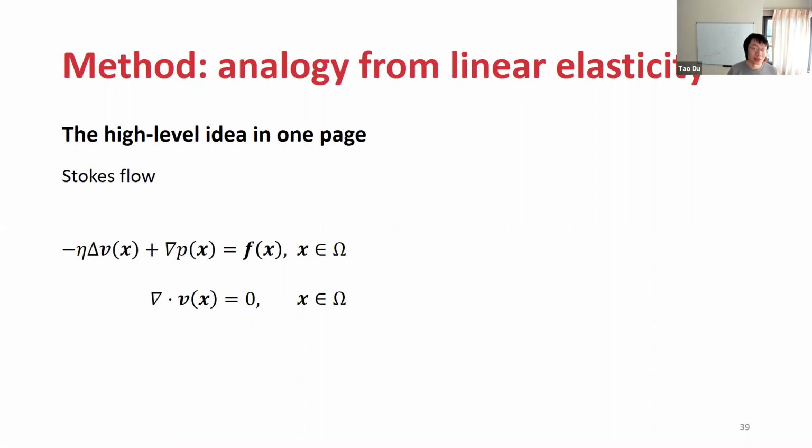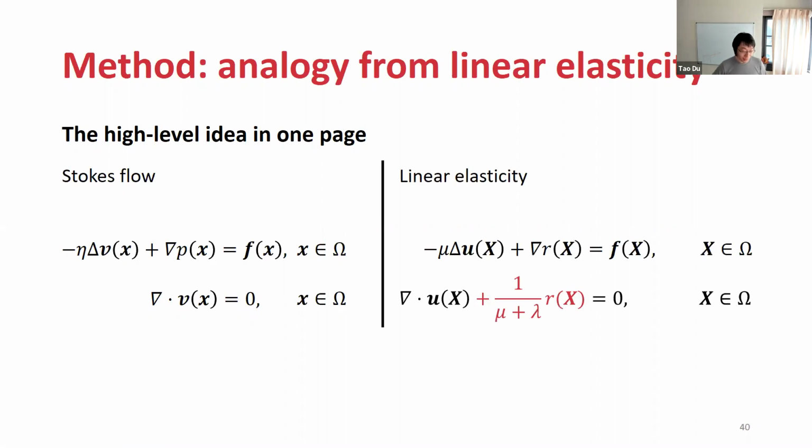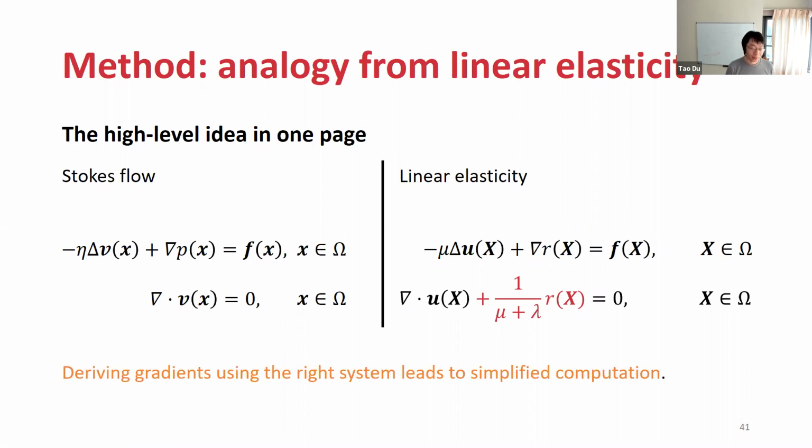In this project, we are considering simulating the Stokes flow, which can be very well characterized by the two partial differential equations here. And one thing we have learned from the prior art is that there's a very strong analogy between the governing equations of the Stokes flow and the governing equations of linear elasticity in soft body or deformable body simulation. And by leveraging this analogy, deriving the gradients using a linear elasticity system can lead to a simplified computation.